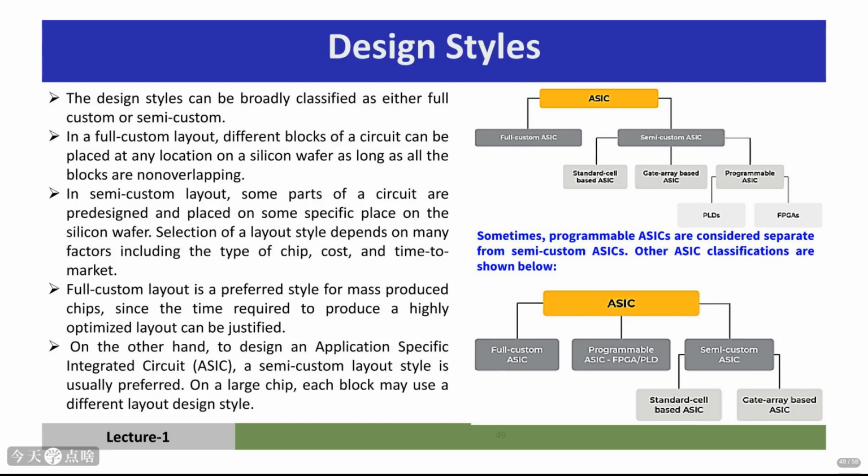Now, let's talk about different design styles. Broadly, we can classify them as full custom or semi-custom. Full custom design gives you maximum control. You can place blocks anywhere on the chip. Semi-custom uses pre-designed components, like standard cells or gate arrays, which have fixed locations. The choice depends on the project type, cost, and time to market. Full custom is great for high-performance, mass-produced chips, but takes a long time.